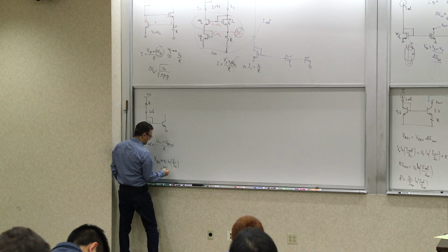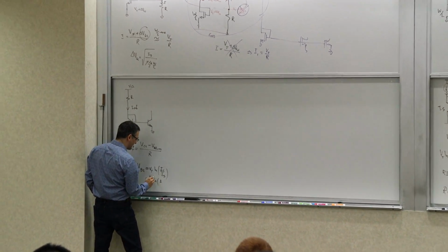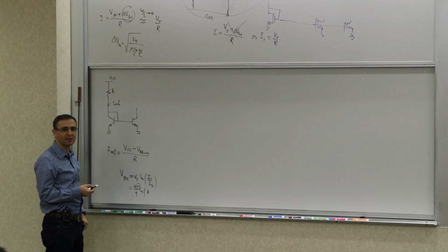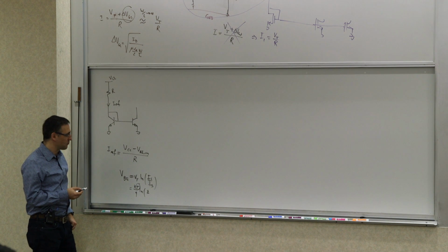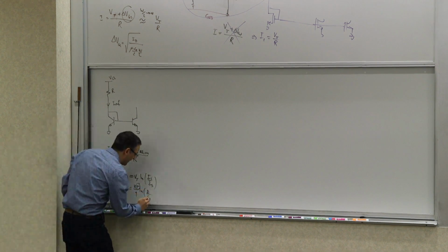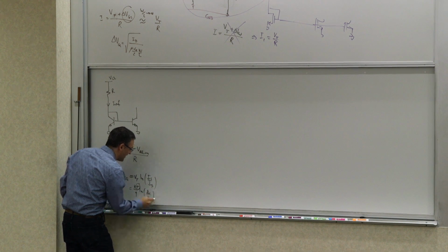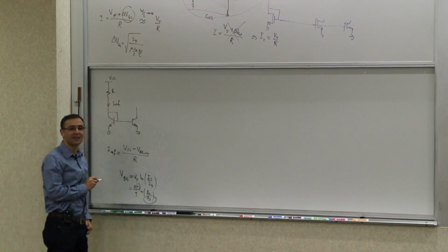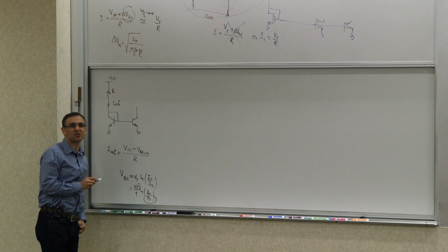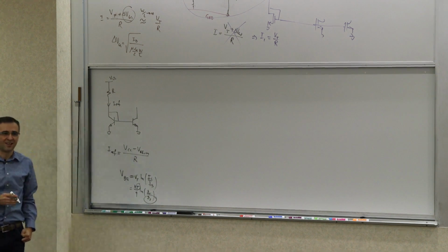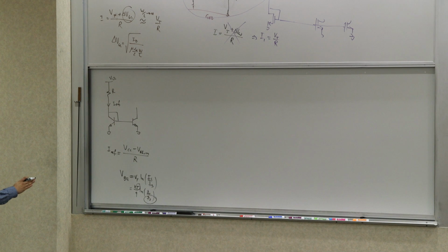And this is some natural log, so it appears that there's a temperature here, so it must be proportional to the temperature, right? Wrong, unfortunately. This guy, this IS, has such an incredibly strong temperature dependence that even through a log, it overwhelms.